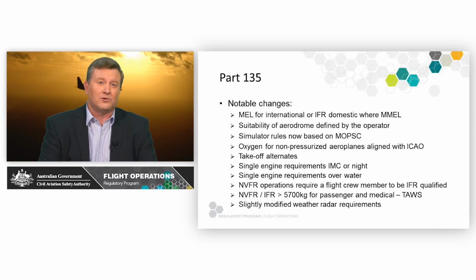We've aligned the oxygen requirements for non-pressurised aeroplanes with ICAO, and that's resulted in some relief compared to our current rules. There's a requirement now, under certain circumstances, to have a takeoff alternate. We've also got single engine requirements for IMC or night operations, where if you're going to conduct those in a single engine aircraft for air transport, then you need to have what in the new rules is called a prescribed single engine aeroplane, which matches up to what is currently termed an acceptor aircraft.